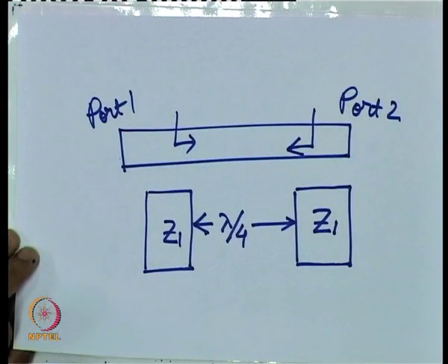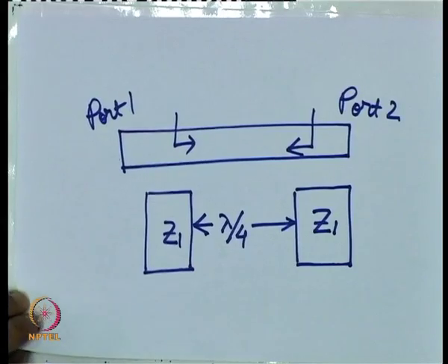Now coming to our bands, I beg your pardon, this was about band stop filters. Now coming to band pass filters, again as I said, band pass filters essentially need a series resonator in series or a shunt resonator in shunt. Since, as I said, a series resonator in series is not possible to implement using microwave components like an open stub or shorted stub, we will go for the shunt implementation.